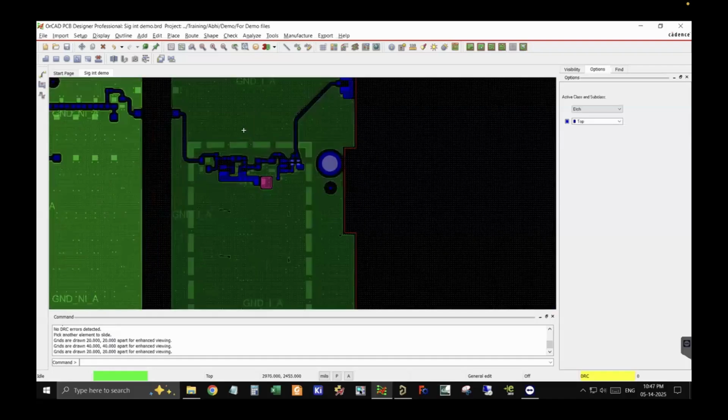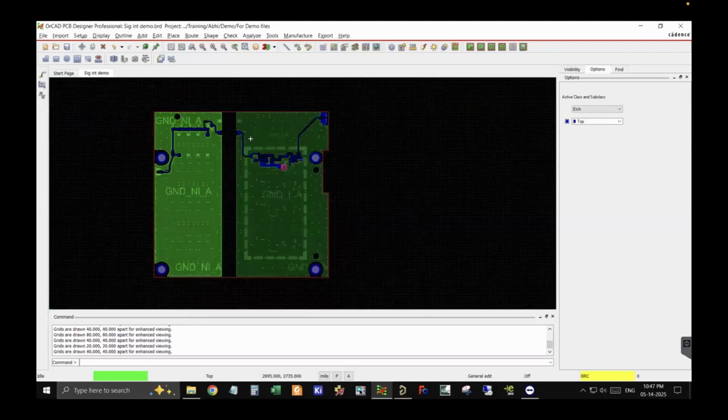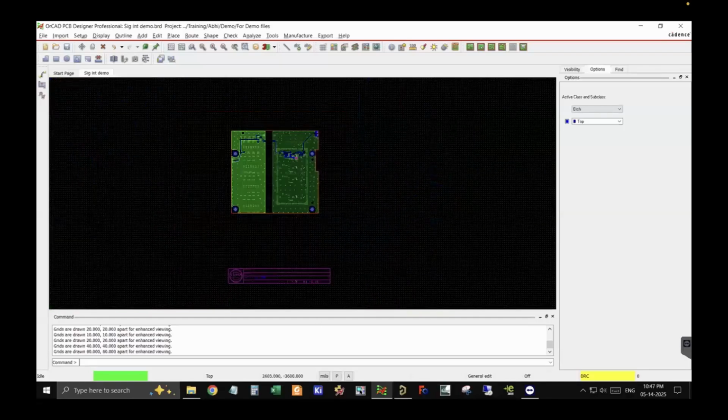And we have used stitching wires, generally to stitch all the grounds properly, so whatever noise that might be involved. Now suppose you don't have enough space for this physical shield, you can also use a virtual shield with the help of wires. Again, the wire spacing would be governed by lambda by 10 or lambda by 20 rule. Yeah, thank you.